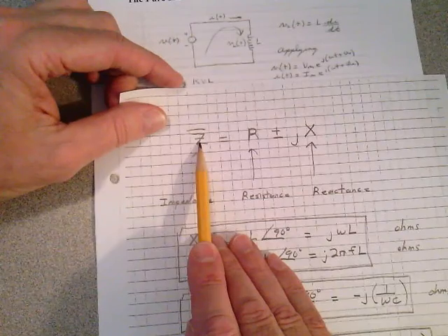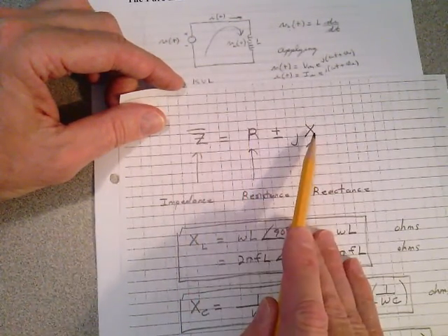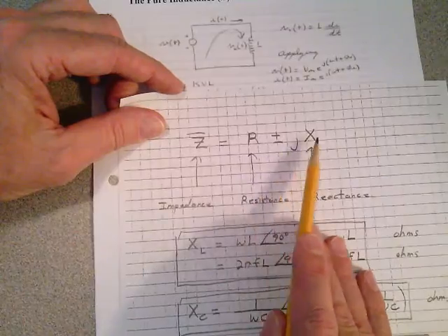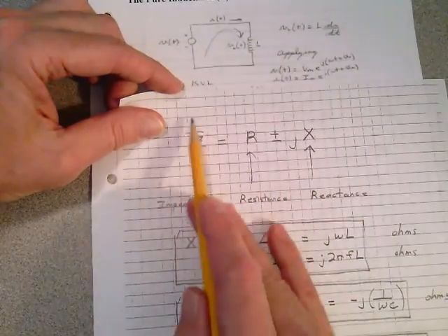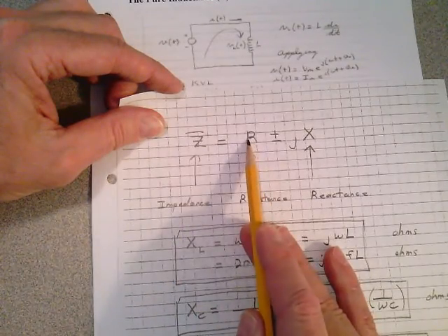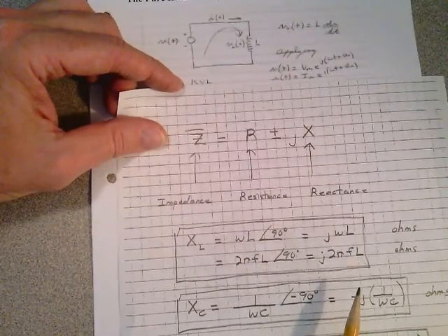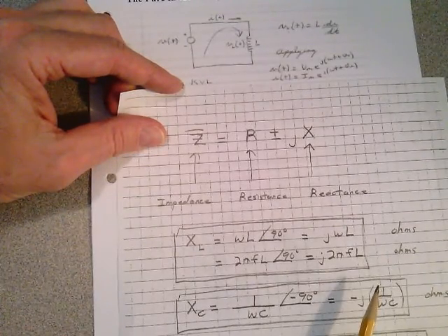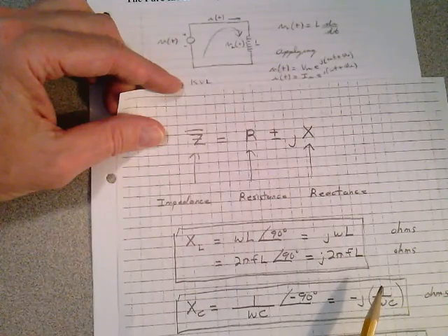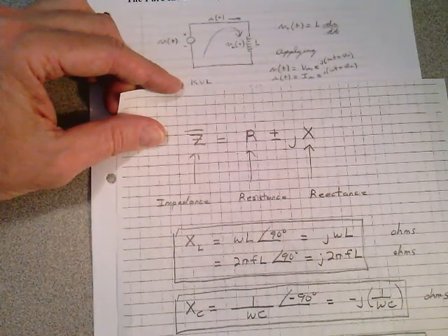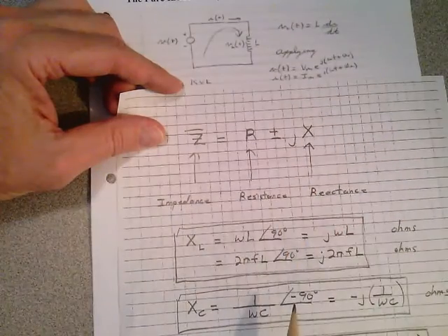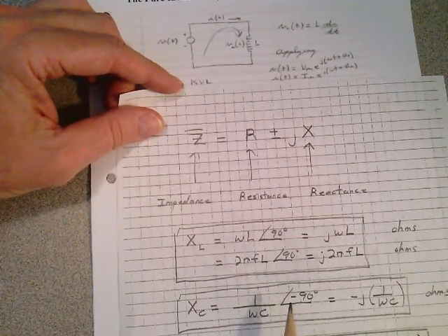This impedance we're going to deal with now can be purely real, or it can be purely reactive, or it can be a combination of both. But there's your complex number. Impedance has a real part, plus or minus an imaginary part. The impedance is the AC resistance we talked about, which is comprised of resistance plus or minus reactance. Your imaginary term is your reactance, but it's not imaginary at all. It's extremely real in electrical engineering. It's either the AC resistance of a capacitor, or the AC resistance of an inductor. This imaginary number is extremely useful. It's not imaginary at all. In electrical engineering, it's very real.